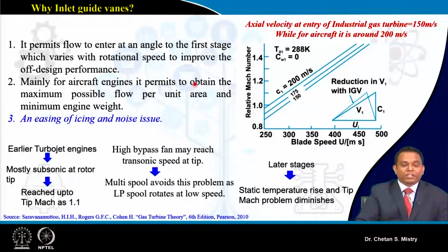Now, as we were discussing, what are the uses of guide vanes? It permits the flow to enter at the right angle for the first stage, which gives an improvement in off design performance. Suppose I am talking about aero engines; these aero engines work under different conditions.